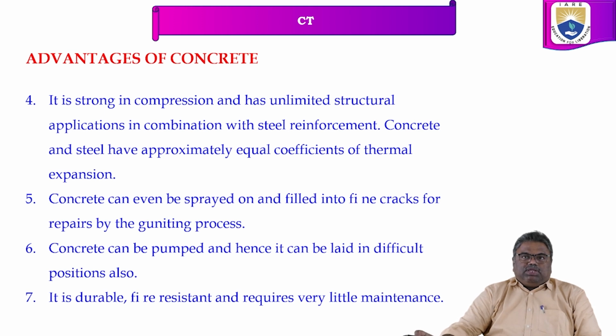Tensile properties are very low in concrete. That is the main disadvantage of concrete. To acquire tensile properties, we have to use steel reinforcement. Concrete and steel have approximately equal coefficients of thermal expansion. Because of that, we are using steel embedded into the concrete.